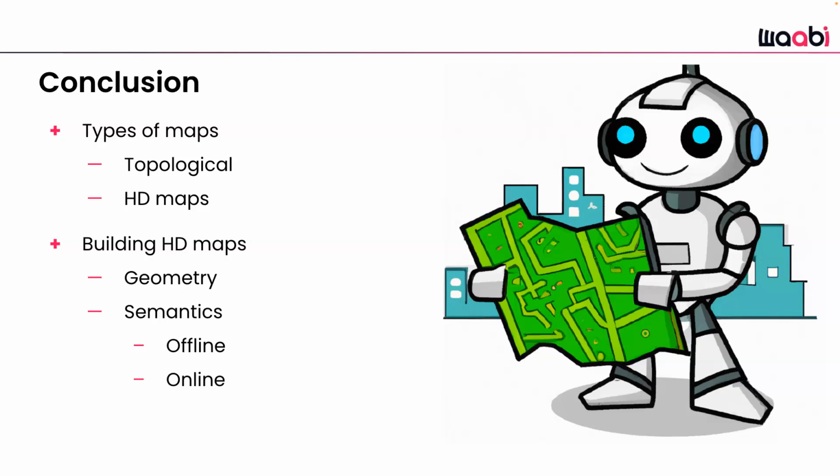Yeah, and of course you can also do it cross-modally. There are some papers that build maps with LiDAR and then use cameras or more inexpensive radars to match against the fancy LiDAR maps. So you can potentially have a mapping fleet with more expensive sensors, and then the production cars that you might sell with assisted driving use more inexpensive sensors, but still leverage these HD maps. Yeah, of course.